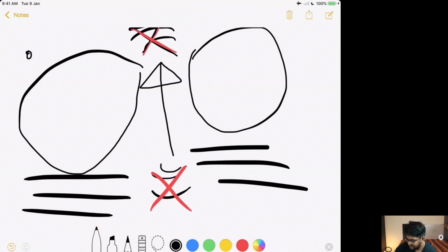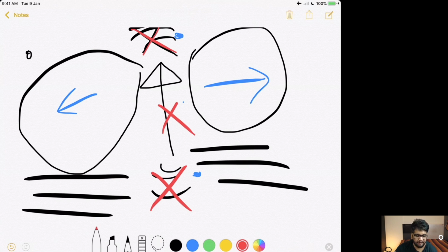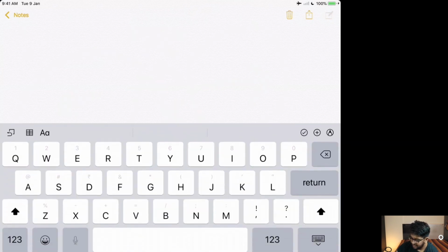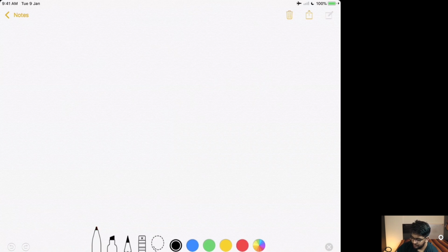So you always want to face your antenna this way if you are flying your drone over here, or if you're flying your drone over here. But as soon as the antenna of your drone comes in this particular direction or this particular direction, it will receive no signal, and it will do something called failsafe, which we will also be discussing in another slide. But just for now, understand that every antenna has a dead zone, and every antenna has a particular shape.